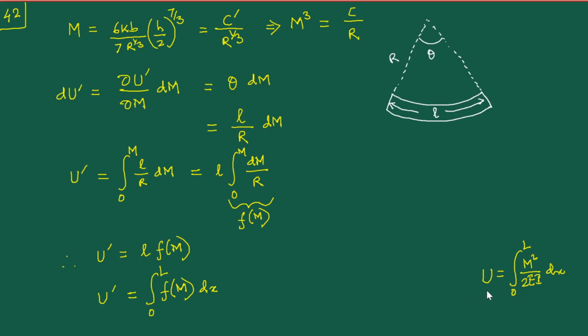For the case of the linear material for a beam, we had obtained this formula, but please note that because now we are dealing with nonlinear behavior, we can no longer deal with this. First of all, we had noted that we cannot even proceed by the route of the strain energy. We have to do with the complementary energy, but you would still like to make the connection with the bending moment. That is exactly what we have managed to do here.